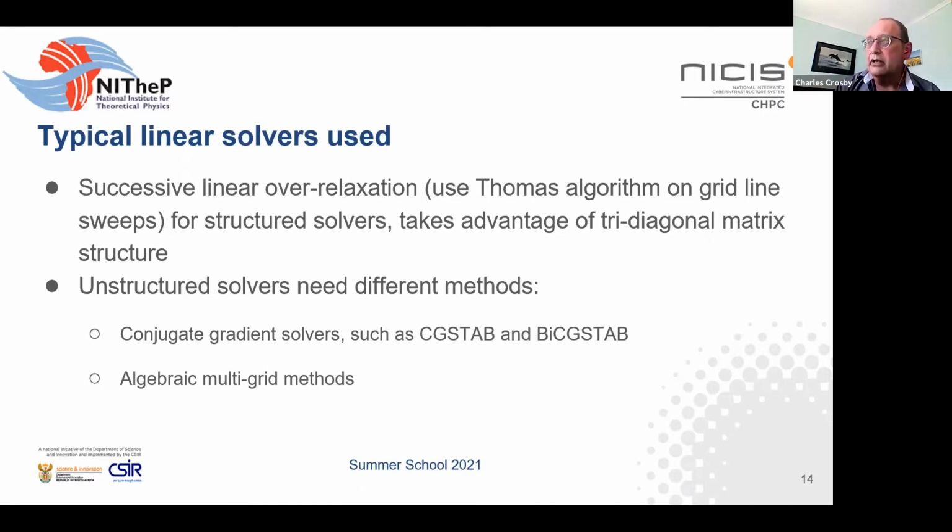In other words, you had to generate a series of grids, and your solution was solved on a sequence of grids of more and more refinement. And you had to be quite careful about assigning your number of grid points on your fine grid so that it could be divided by 2 a number of times to coarsen the grid. Now, mercifully these days, the algebraic multigrid solvers take care of that at matrix level. So you don't have to worry actually about the grids themselves, about coarsening the actual grids.